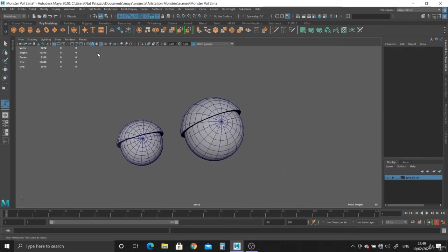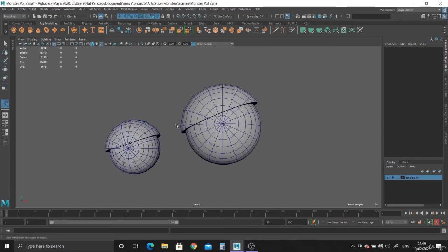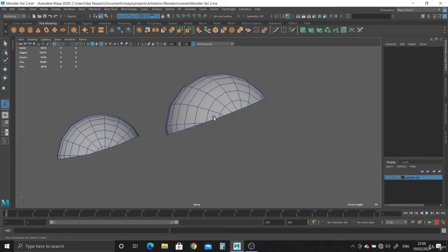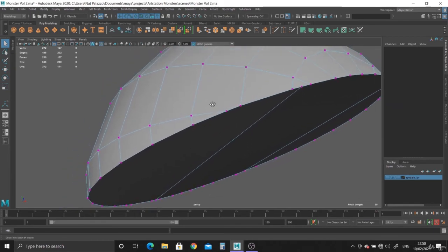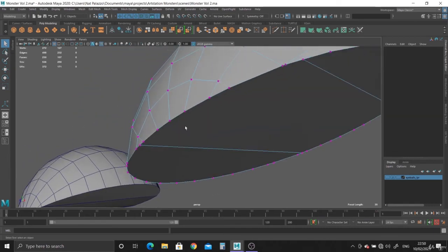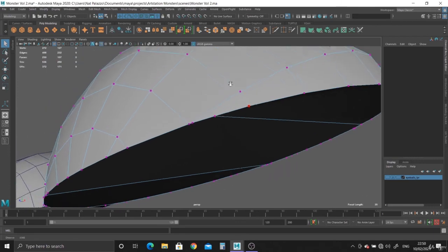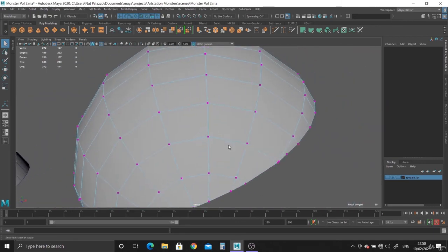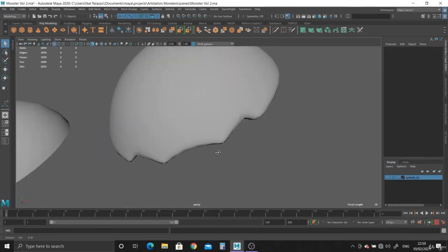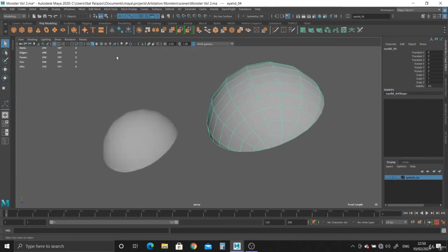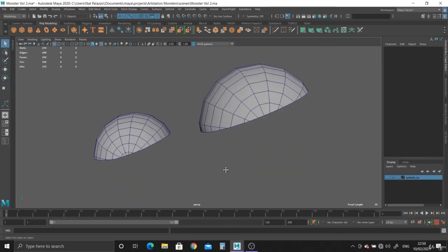So we've started to create the eyelids. There we go. Obviously we're not finished yet, because if you take a look at the geometry here, it's not working, as you can see, because you need nice soft geometry, and the only way to create nice soft geometry is to make sure that your vertices and your edges all connect to create quads, and quads are four-sided shapes. If not, and you hit 3, you get this ugly thing here, which is not very good, and we will deal with cleaning it up later. But for now, there you go, we have blocked out the eyelids, so I will see you next video.